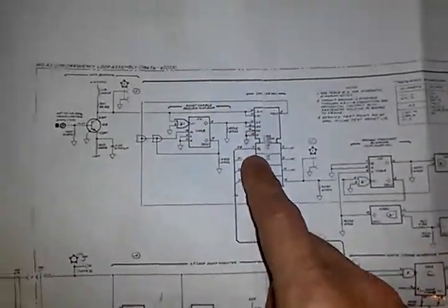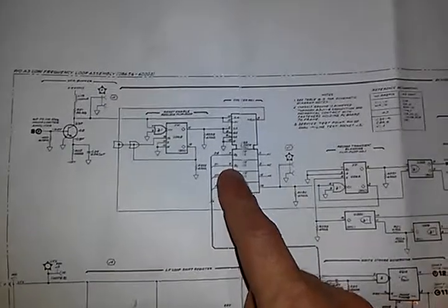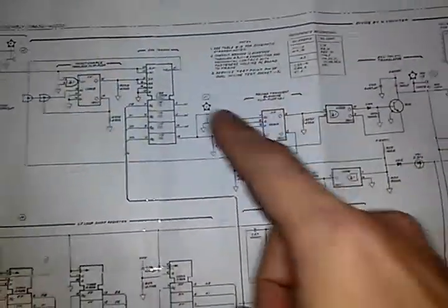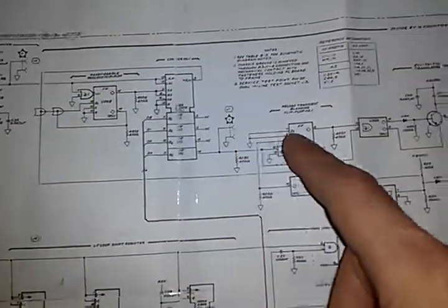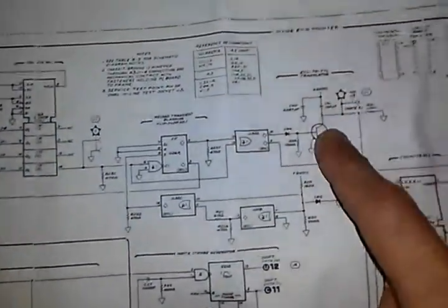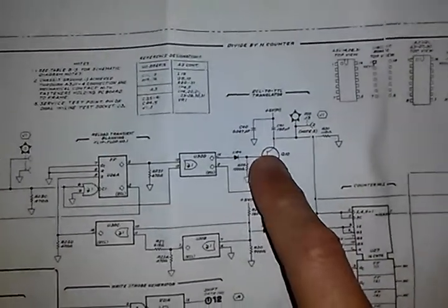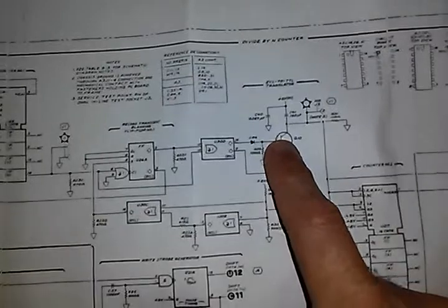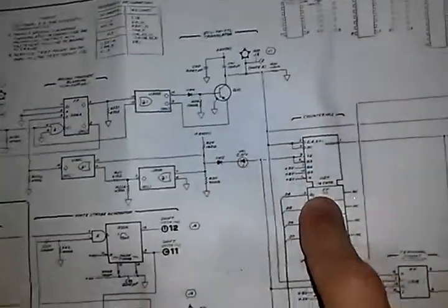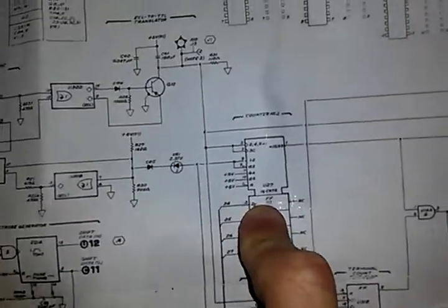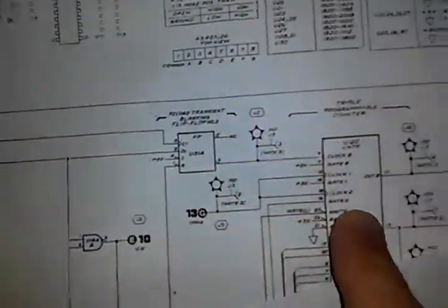And the way it works is that you have one counter here, which is basically a divide by 16 counter, and it's programmable. It doesn't always divide by 16. This is an ECL counter. It goes through these various stages to a logic level changer. This here changes the logic level from ECL to TTL. Then it goes to a second counter. Again, divide by 16 generally, and I'll get into that in a second. Then it goes to a third counter, which is this U20, if I'm not mistaken.